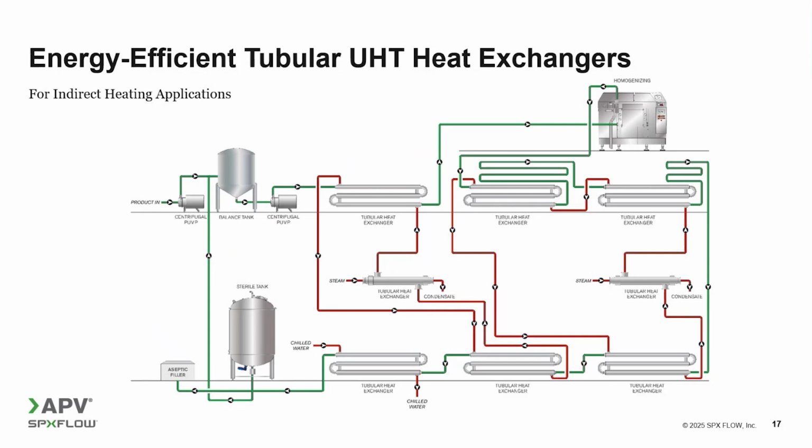That would be ideal for recovering heat from the product in a more efficient way. So, by having this separation, that would allow us to have improved energy efficiency because each water loop would be probably operating closer to the ideal temperature range.